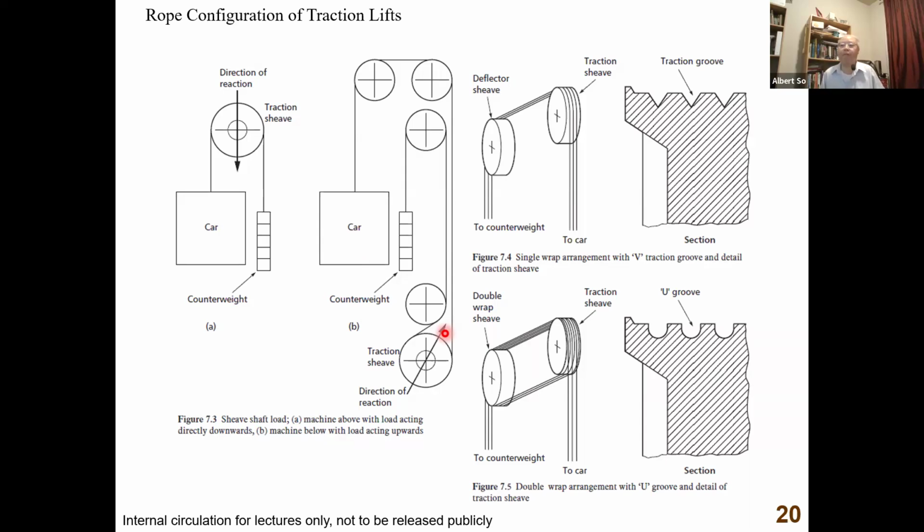Because of the old airport, there's a height limitation of buildings in Kowloon City, because it's below the path of the aircraft. So you try to limit the height of the building. So no machine room on top of the buildings. Then they have to build the traction sheave and the motor down below, in the lift pit.